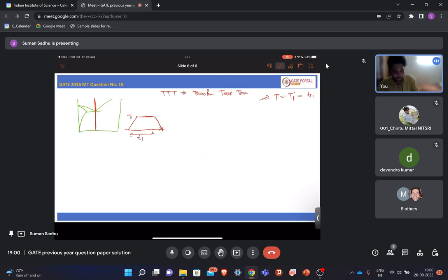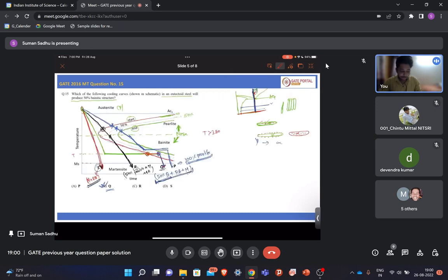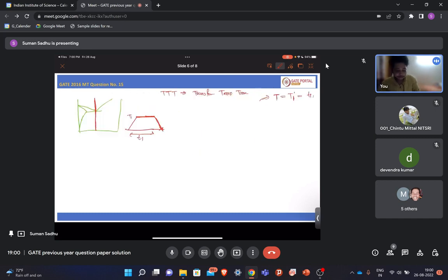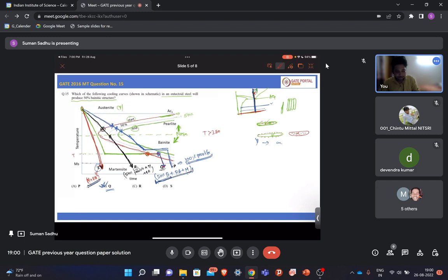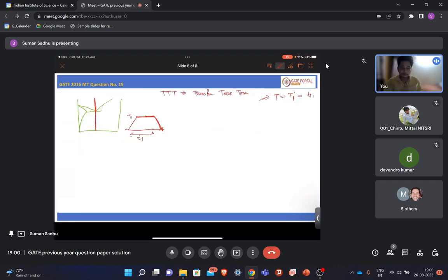So quenching means the microstructure formed at this holding period will be retained. It may also transform to martensite, but that pearlitic fraction that is present, as given here in the curve, will not be affected, because upon quenching that pearlite will not change, right?